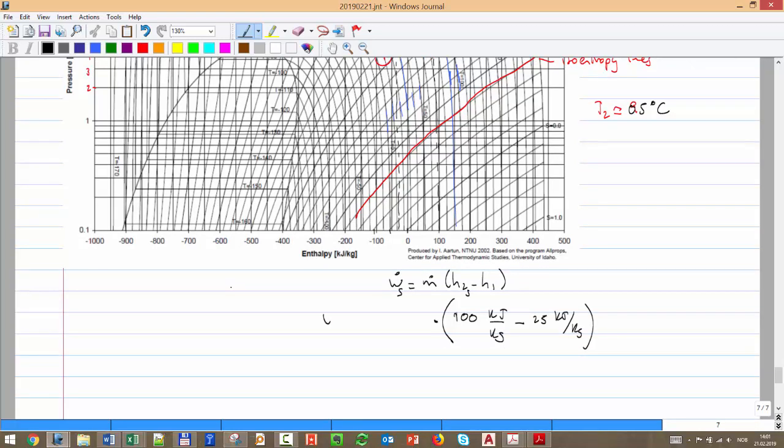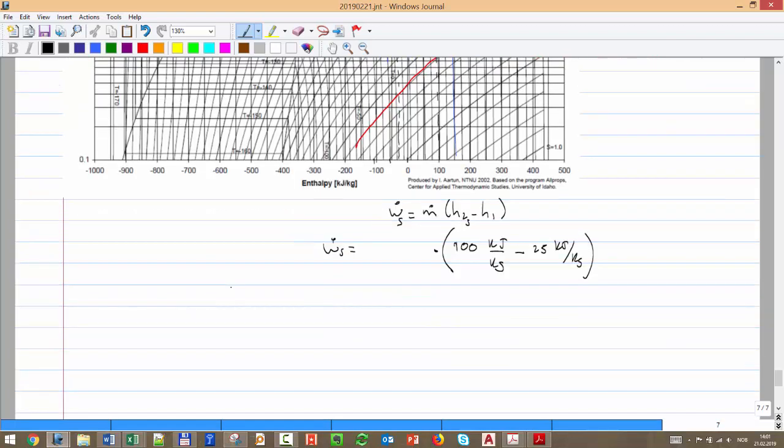What is the mass flow that I have? How much was this field producing at plateau rate? It was 10 million, right? So the Q of the field was 10 million standard cubic meters per day. How much is that in mass flow?